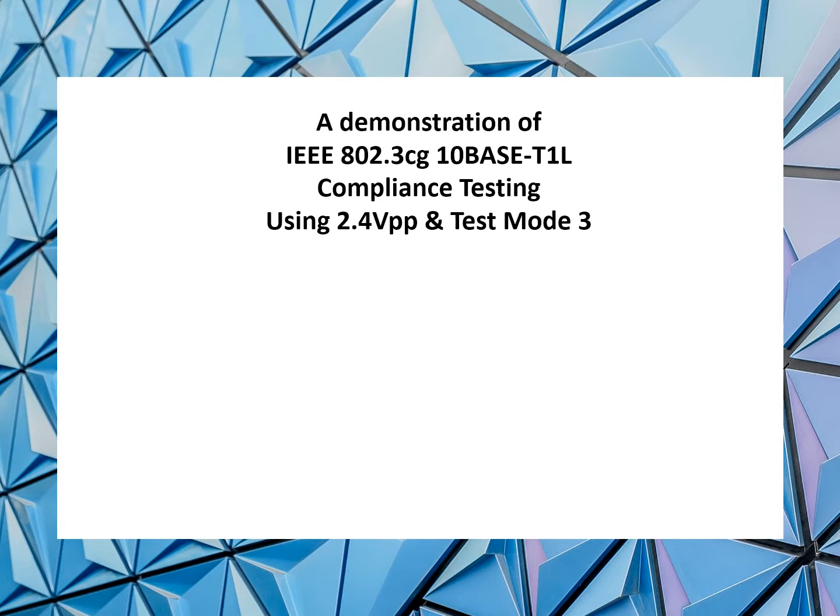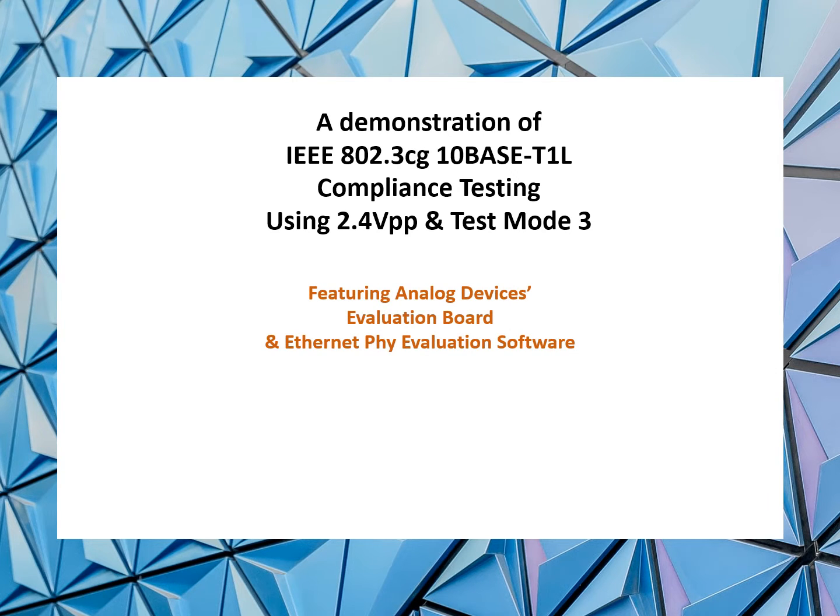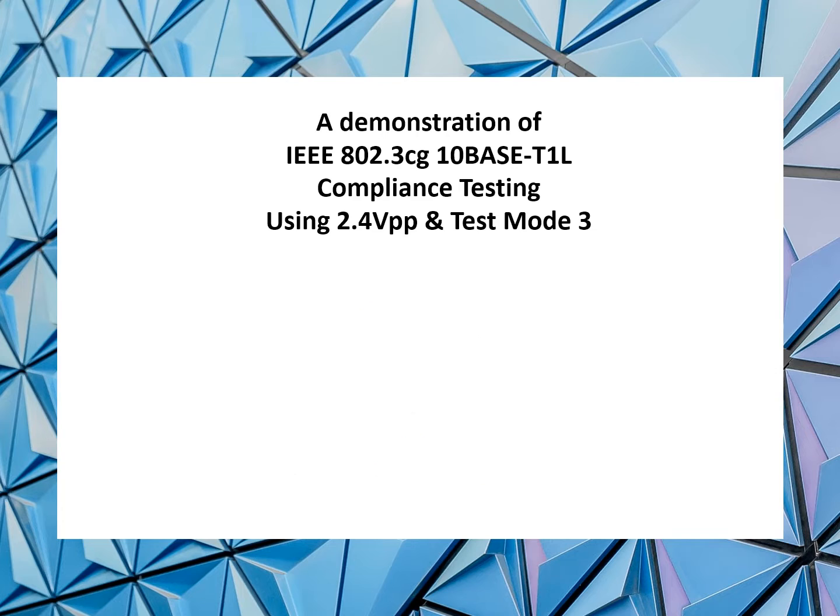Welcome to a demonstration of IEEE's 802.3cg 10BASE-T1L compliance testing using 2.4 volts peak-to-peak and test mode 3. This demonstration will feature Analog Devices Evaluation Board and Ethernet PHY evaluation software with Telebyte's digital analyzer, probe, and software.